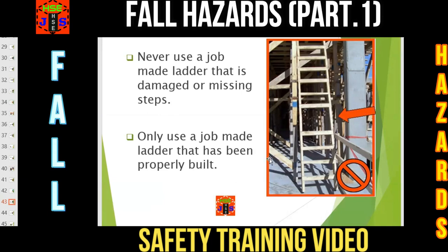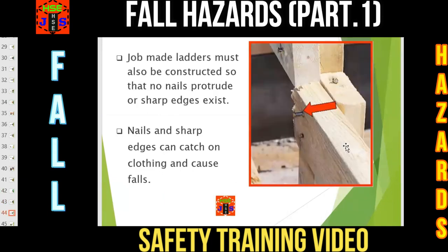Only use a job-made ladder that has been properly built. Job-made ladders must also be constructed so that no nails protrude or sharp edges exist. Have a look. Protruding nails. Nails and sharp edges can catch on clothing and cause falls.